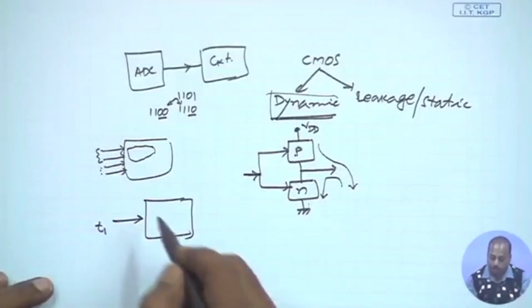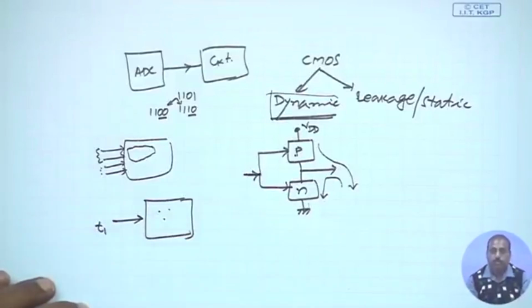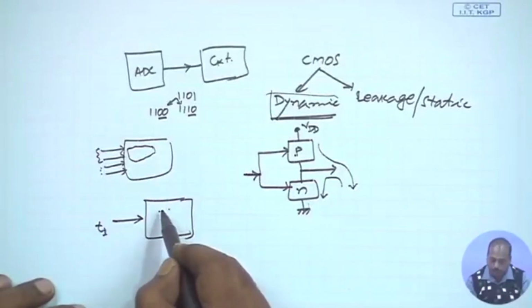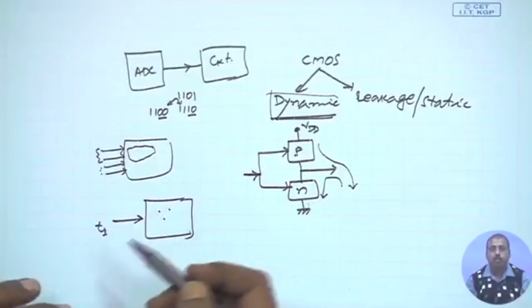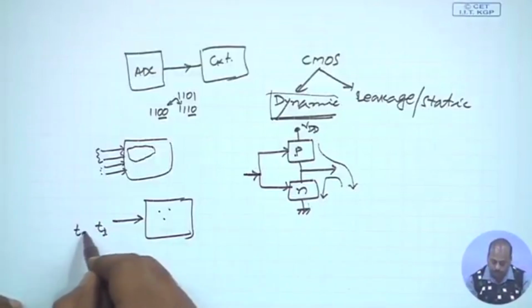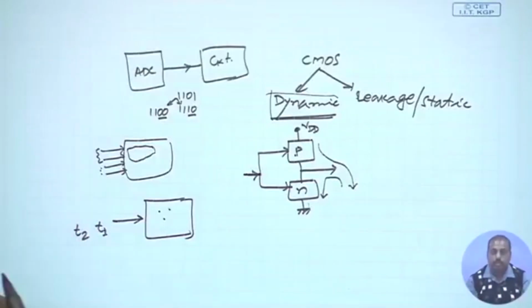okay. So it detects say these 3 faults. Now the second test pattern, if it is similar to T1, then what will happen? It will possibly detect say these 3 faults and maybe some more faults or maybe fewer faults, that way it will work. But it is very much unlikely that it will detect a drastically different set of faults if the second pattern T2 is very much similar to T1.